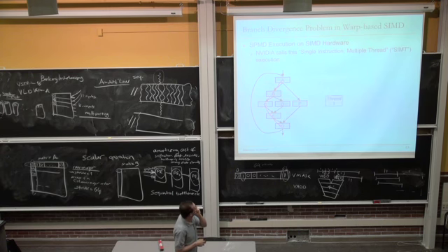What might happen is you have different threads, and you group them into a warp starting from this location because they all have the same PC, program counter. Thread 1 may go this way. Thread 2 may go this way. Thread 3 may go, well, it happens to go the same way as, I guess, thread 1 and thread 2. And thread 4 may go this way.